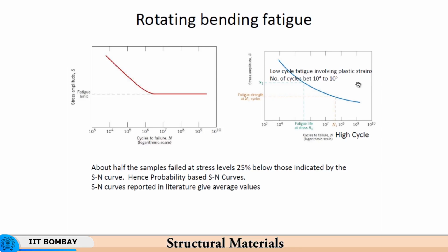So if anything is designed for infinite fatigue life, as it is called, then you take the working stress to be this so-called fatigue limit. This is the maximum stress to which you should subject the material, so that it withstands stresses for a lifetime. With a factor of safety, you can almost be sure that it will last forever without having to be replaced.